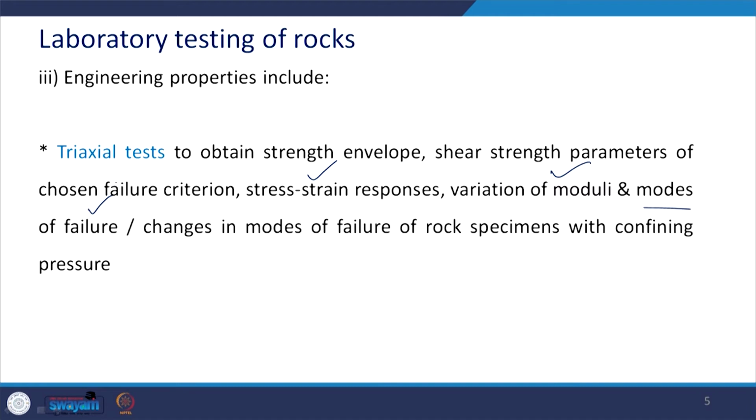Like if we test a specimen at low confining pressure or at high confining pressure, there is going to be a change in the mode of failure. So, this triaxial test gives me an idea about all these parameters.